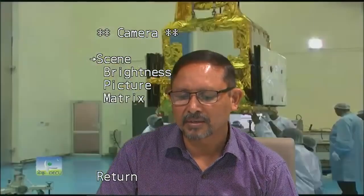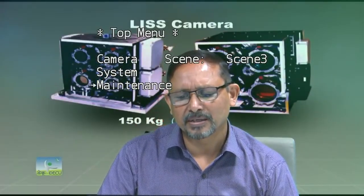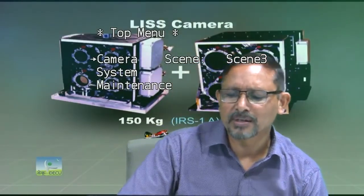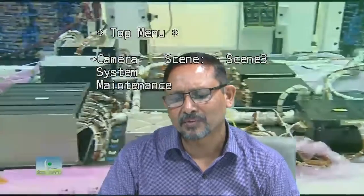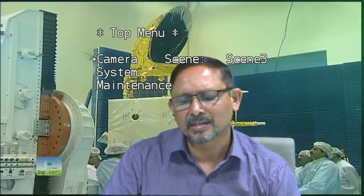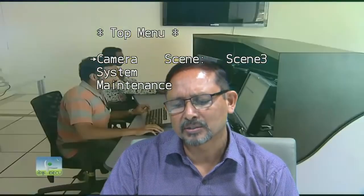One question is whether sedimentation deposited at the outlet can be interpreted. Not directly, but with terrain analysis you can find out which part has more chances to collect sedimentation, where sedimentation deposition will take place. I told you about the stream power index and terrain wetness index. By integrating both you can interpret which area will receive more sedimentation because of depressional area, and which area is upland area where you can expect less deposition or no deposition. So by terrain analysis you can do this.